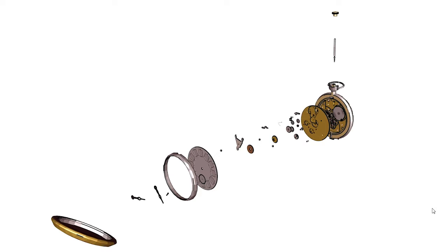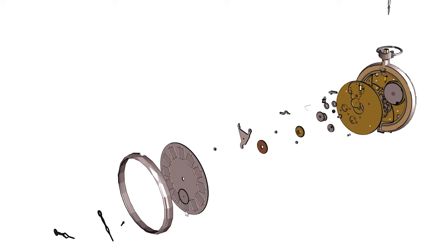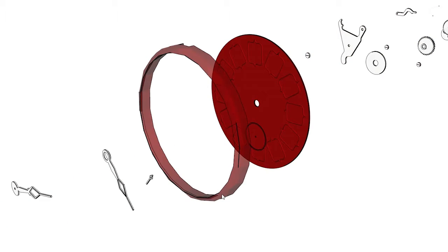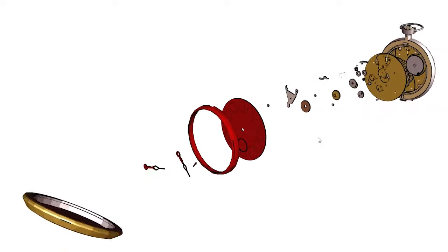As part of disassembly sequence editing, we support interactive partitioning to create subassemblies that restructure the hierarchy of an assembly. During sequencing, each subassembly is treated as an individual entity until it has been separated from the remaining structure. Therefore, the way in which an object is partitioned can influence the disassembly sequence.